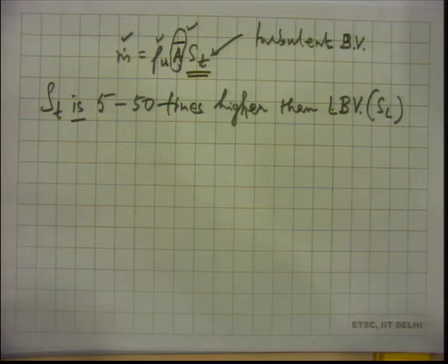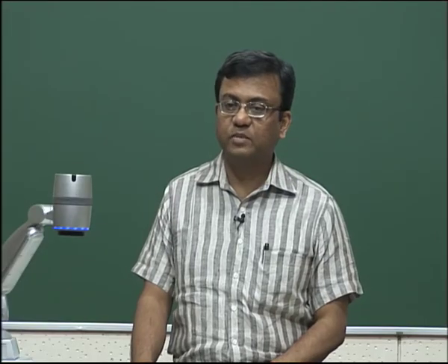That is actually good, because if you have a burning velocity which is really high, then that is good for industrial applications, that is good for engines. If you try to run an engine, let us say a spark ignition engine which employs laminar combustion, then you will have a very hard time because the burning rates are low. So, turbulence increases the burning rates,